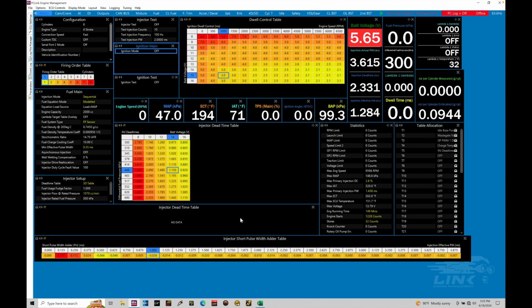So different coils, say we're dealing with something like a Honda K series coil, or a Denso Prius coil, or an LS, let's say LS2 base coil. They all will have different coil dwell because the actual coils internally are made different. So the dwell table is important to be able to characterize which coils we're using. Same kind of idea as when we were programming our injector data, looking at something like our latency dead time values that is characterizing the response of the injector. The coil dwell is going to be how we actually characterize the charging characteristics of the coils we're dealing with.